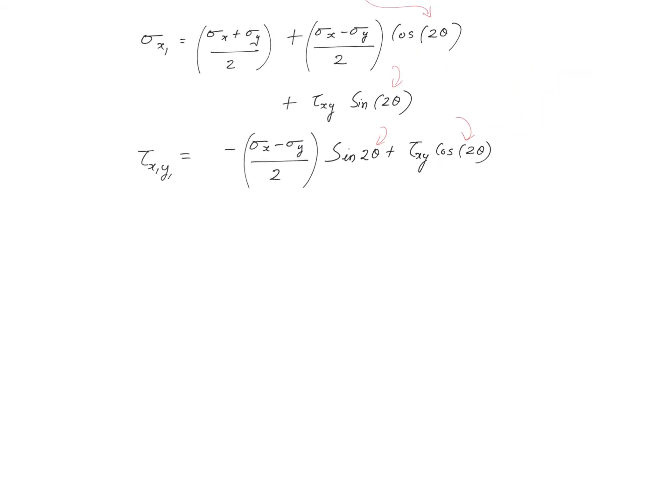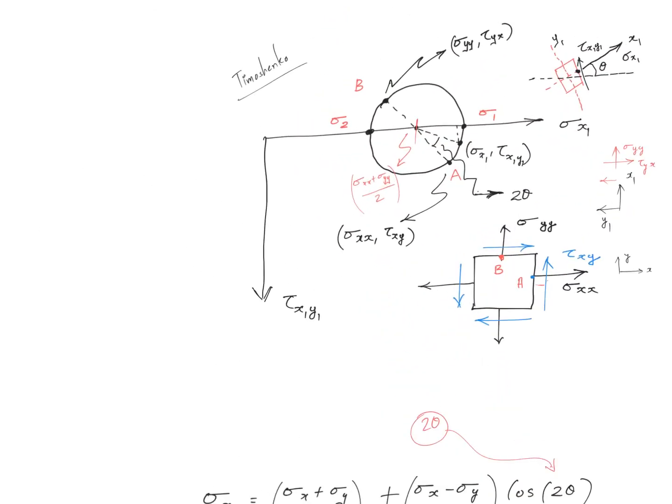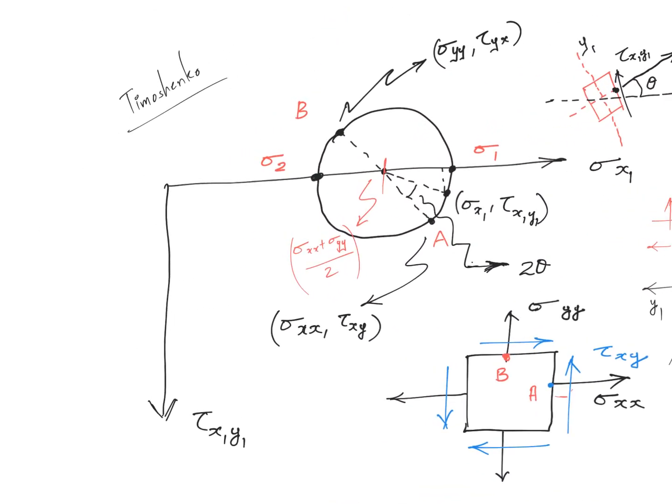Finally, we have expressions for the principal stresses, which is simply the center plus the radius, and center minus the radius is the second principal stress.